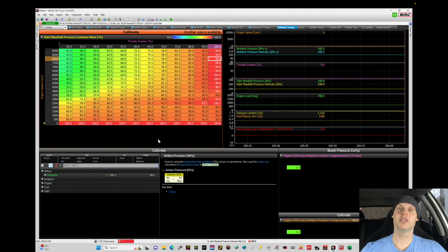We're going to be taking a look in this training module at how to dial in high cam or VTEC operation. So looking at fuel, spark, and variable cam control, and also setting our VTEC engagement point. Now we've dialed everything in for the low cam or non-VTEC, so we're going to be learning how to turn on our VTEC, how to configure our VTEC output table, how to figure out what the ideal VTEC point is going to be, and then map out fuel, spark, and variable cam.